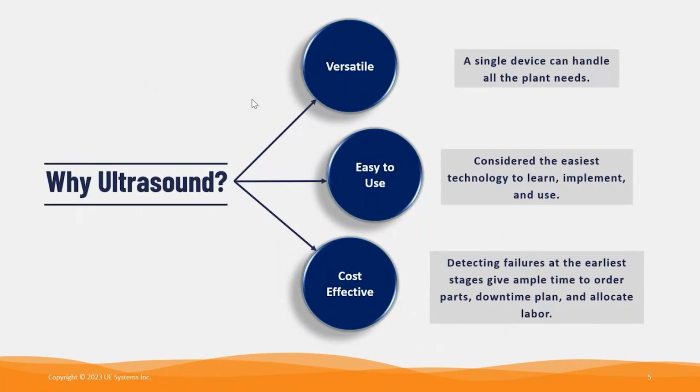The first answer that comes to my mind for this question is that because it's so simple. You can listen to your equipment as if you gave it a sound to tell you what's going on inside. You can listen to friction levels, identify if there is contamination or bearing defects, and can easily distinguish the healthy bearings from defective bearings, for example. The ultrasound technology is also cost effective. For example, leak detection is a very easy application that can save you a lot of money as it optimizes performance, efficiency, spare parts for the compressors, and so on. So money-wise, this will be very helpful for your facility.